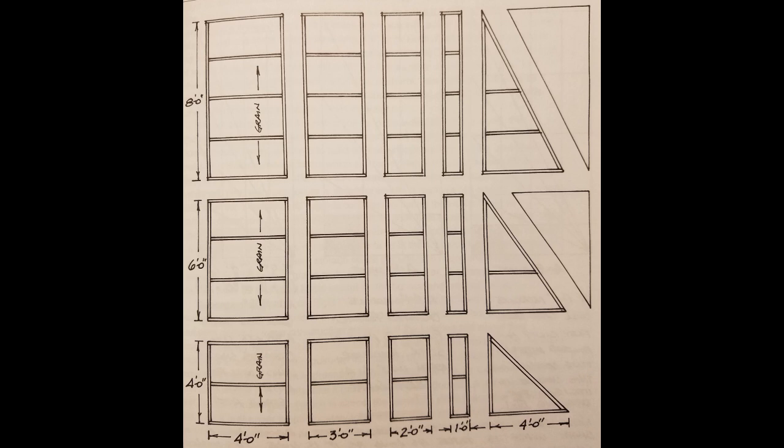Now, while most platforms that we will be using or see in theater are mainly built out of lumber, there are other types of material that we could build from. Metal platforms can be the most sturdy and the most rigid simply because of the stress and breaking strength of metal versus wood. It tends to bend less over a period of distance without being supported underneath, but they are a little more time consuming to build and require the use of welding tools in order to build them.